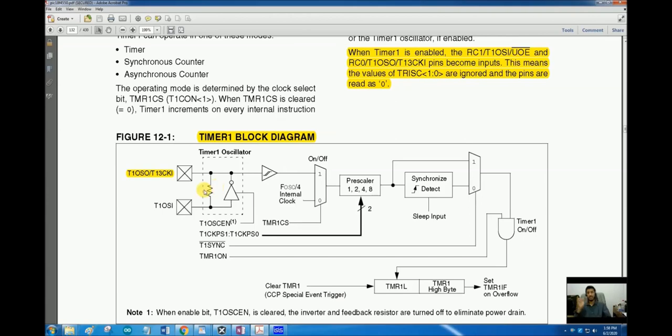But if we use the internal crystal oscillator of the system as the clock source to the timer, we cannot precisely set the delay. And if any of you has happened to open an actual wall clock or an actual digital clock, you could see that there is a small silver color crystal oscillator inside, and on that crystal oscillator there is written 32.768. 32768.